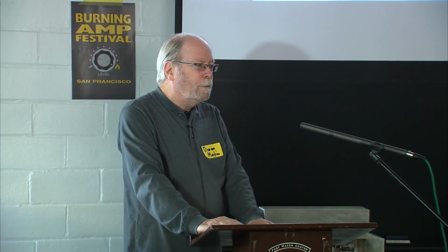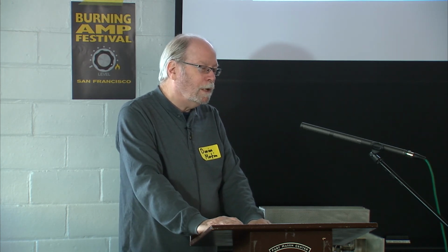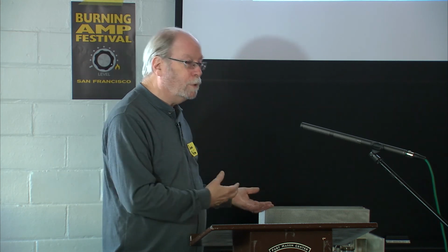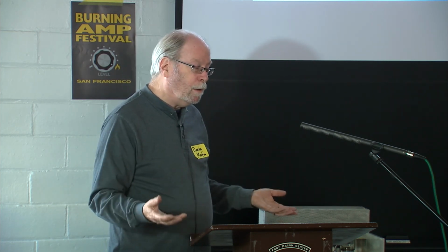Well, if you're trying to emulate a speaker, yes, it makes sense to have a resistive and inductive load, because speakers are inductive as well as resistive. And if you want to see what's going to happen, particularly with a switching amplifier, depending upon the design, you could run into instability with an inductive load, because of the feedback and the way they work. So it would make sense to do that. But if you're just going to measure the power output, I don't know why you'd do that unless you're trying to dodge something.